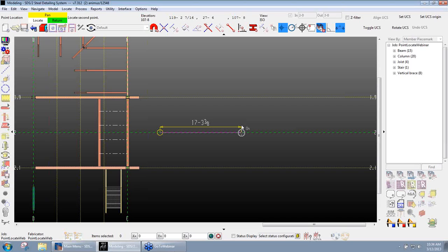Another thing that is new here is once I select that first point, notice as I move my mouse around, it's going to snap to and create temporary construction lines every 45 degrees. So notice when I swing around here, it gives me that temporary construction line. Here I got one at 90, again at 45, and then at 0. So temporary construction lines get created at 45-degree increments.